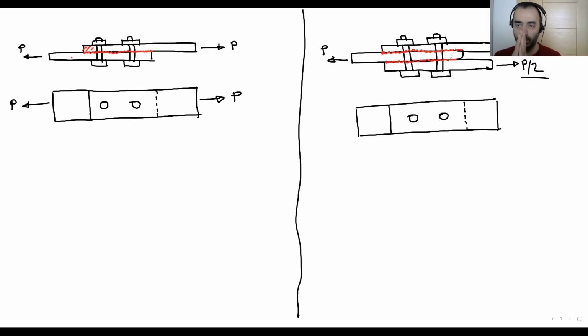So here in the first case, there are 2 plates touching each other. That is the shear surface for my calculation. For the second one, there is a top plate and a bottom plate. They touch the mid plate from top and bottom. That means there are 2 touch surfaces. So these are the shear areas. We have 2 shear areas.